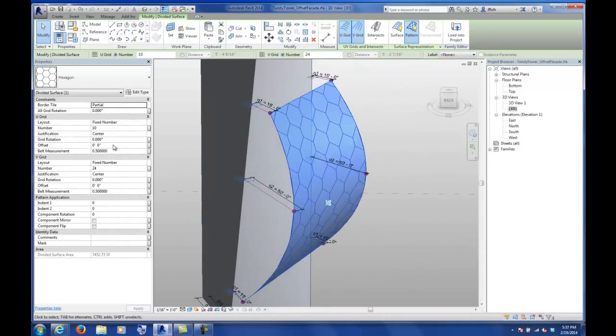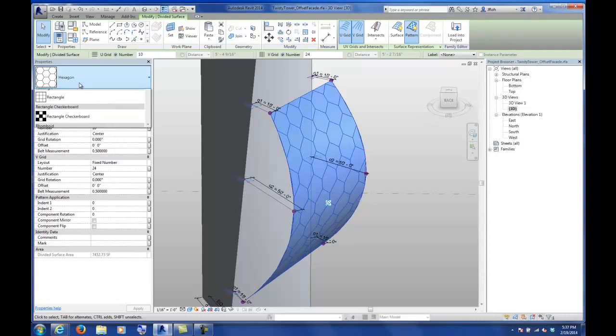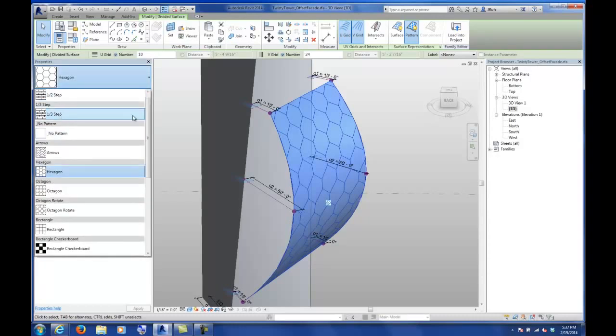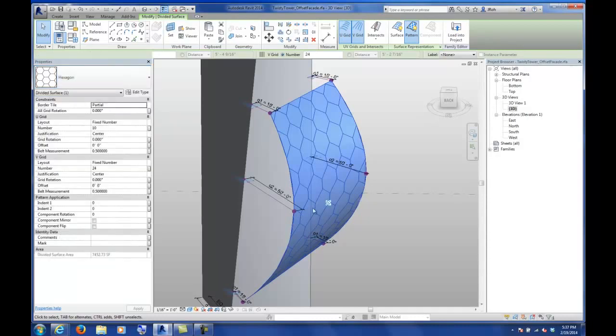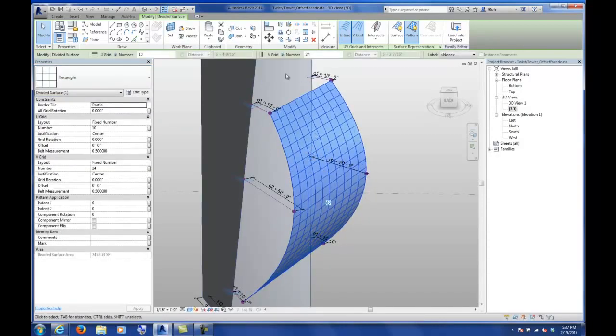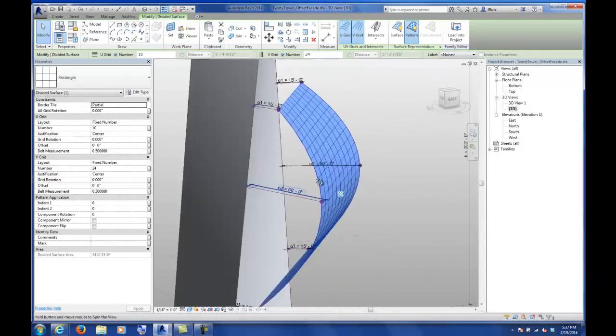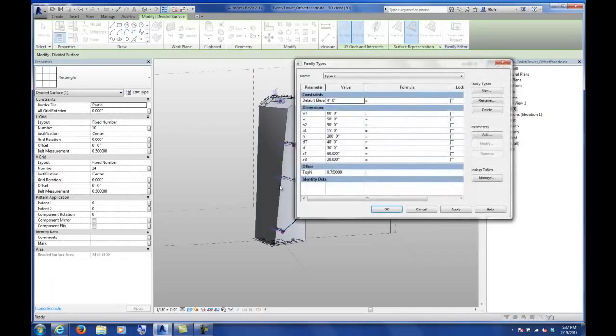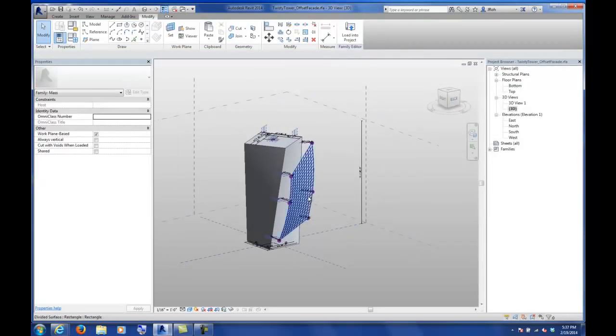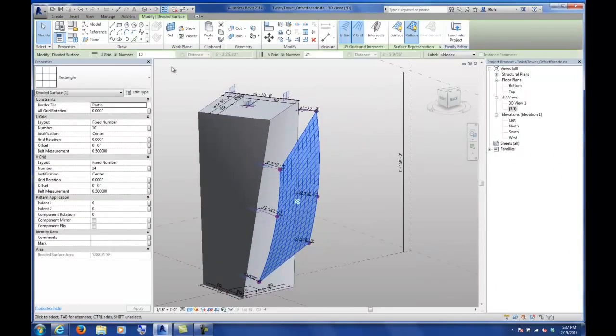So yes. If you went back and changed those offset 1 and 2, would you have to readjust your grid numbers? Right. So again, to take this to another level, right now I've done all of these U and V grids that are associated with this particular surface, and that's actually a good question, is that when I change my particular tower type, so when I go to Tower 1, I still have the same exact number of divisions.